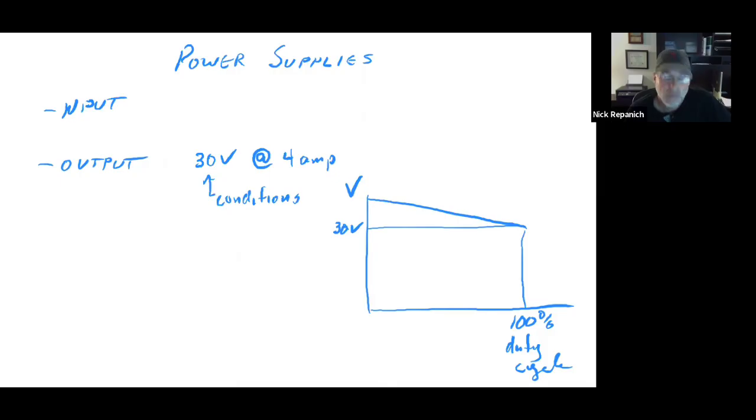But at no load, over here, at 0, you can go measure it. It's probably closer to 37 volts, which is a problem. That's a tricky thing about these linear power supplies that do well with inductive loads, is that they're variable and they vary under load. It's a big transformer under there that in and of itself is an I squared R loss. And so the more current you put through it, the more it draws the voltage down. And so it's rated, usually the words rated,